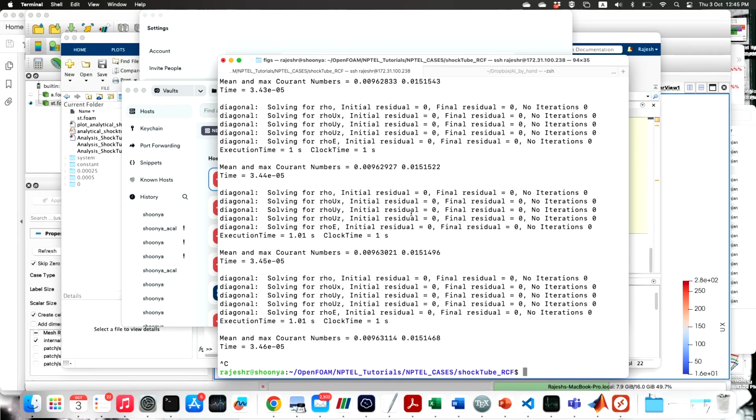Okay. So, here this is a density based solver, unlike sonicFoam which is a pressure based solver. There we saw that we are solving for ux, uy, uz and then p and e, right. Here it is a solver that we have been discussing a lot in our course, right. You are solving for rho, which is the continuity equation, and rho ux, rho uy, rho uz. Okay. So, it is solving in the conserved manner. Okay, and finally, the rho e, right. So, it is solving for all 5. So, this is I think the only solver in OpenFOAM which is density based. Of course, there are more solvers which are coming every day, right.